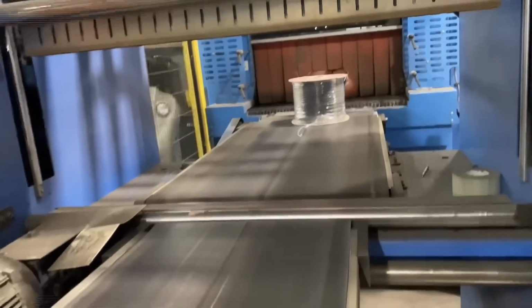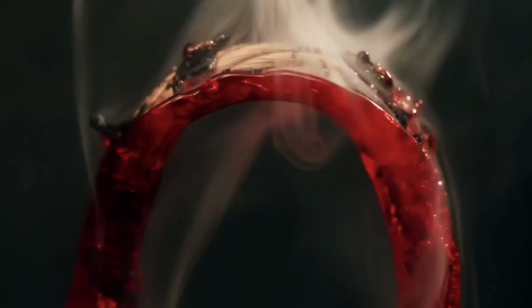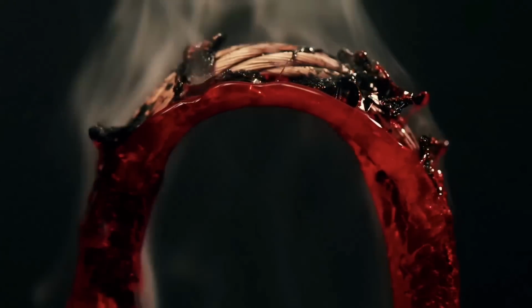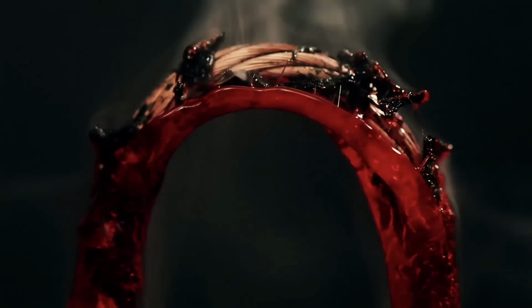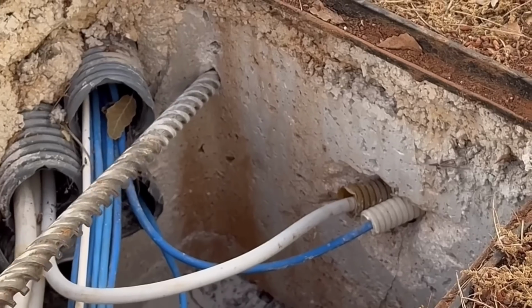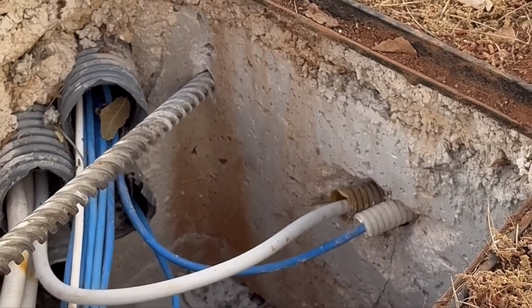That's what causes a motor to burn out. Too much current flows through the winding and melts the insulation, leading to that all too familiar fishy smell and smoke coming out of the motor. Of course, this can happen on handheld tools as well. If you're asking a drill to drill holes that are too big or run it for too long under pressure, it too will overload and burn out.